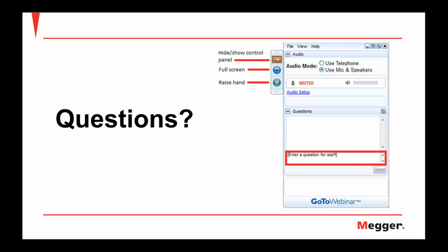As I'm going through the string measuring NiCad batteries with an impedance tester, if I see some that are much higher, real high compared to the others, that's a flag already that that cell has a problem, okay? But if I see they're all pretty close to each other, it doesn't mean that they're good. You still have to do the discharge test.